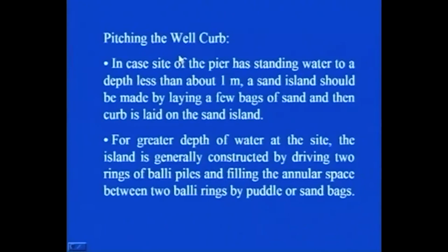Now, what happens if it has standing water? In case the site of the pier has standing water to a depth less than about 1 meter, a sand island should be made by laying a few bags of sand, and then the curb is laid on the sand island, because it needs some base to rest on. So, that is why, if the water has a depth of less than 1 meter, then sandbags can be used.